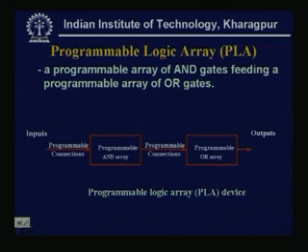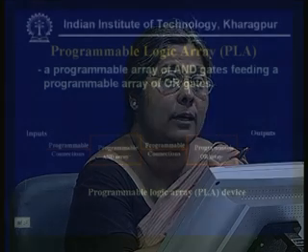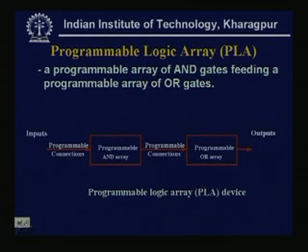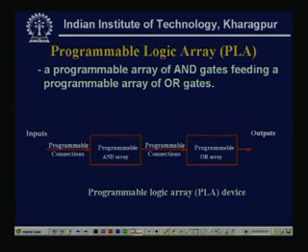Now, we see the programmable logic array or the PLA, and as I already mentioned, the programmable features of PLA are the maximum, because it has two planes, and both the planes are programmable. See here the AND plane, this is my AND plane, this is also programmable, and this is my OR plane, that is also programmable.